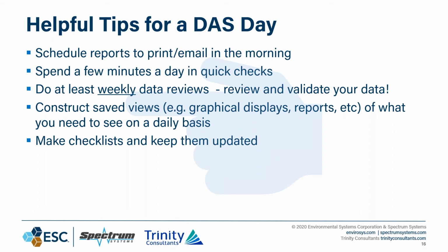Thanks, Adam. Some helpful tips for a DAS kind of day. As an efficiency measure, schedule your reports. If your DAS has the capability of doing this, and most of them do in the 21st century, you should schedule your reports to print or email in the morning. And spend a few minutes a day on quick checks. You should be doing at least weekly data reviews. Review and validate your data. Make every status flag make sense.